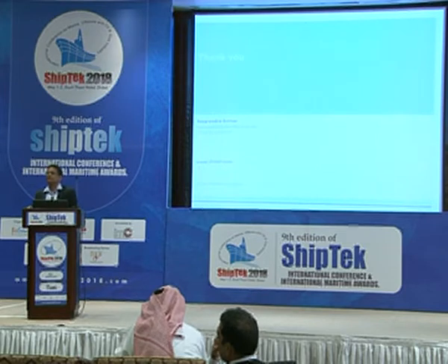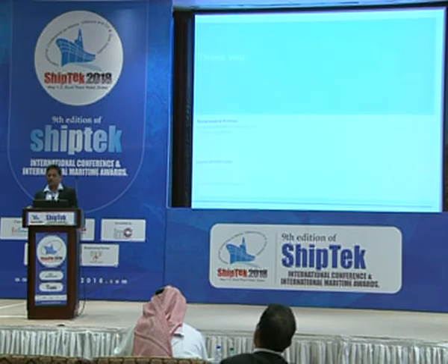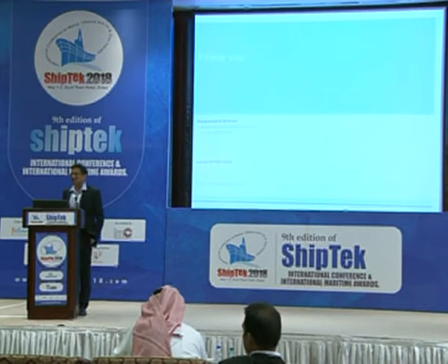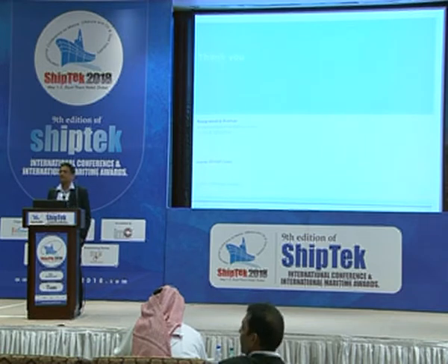Just to be very specific, in the last 24 months, have you postponed any survey which required a 5-year survey, and have you postponed to 6 or 7 years? It has been done on a case-by-case basis, but it was not through machine learning. It was mainly through RBI, risk-based inspection, and I am not aware on the ship side. I work mainly on the offshore class side, so I think it has been done for a few of the jackups. Yes, that was based on the RBI studies.